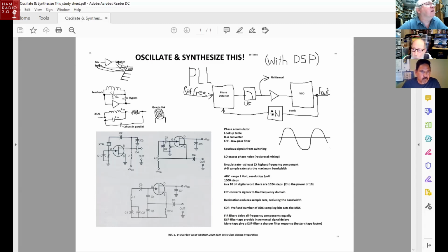But when the sound comes out of the speaker, that's the top left of the page I'm looking at. Everybody knows that this little triangle with a line in and a line out is an amplifier. Sound comes out of the speaker, bounces off the wall, gets back to the microphone by whatever mechanism. The microphone's pointed toward a wall that the sound is bouncing from back to the speaker. The mechanism of producing the howling noise is feedback. The noise you hear is oscillation. So we need to get those two concepts separated.